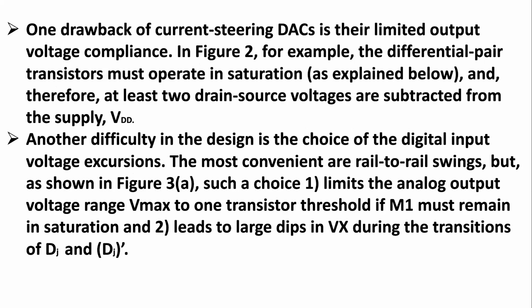In figure 2, for example, the differential pair transistors must operate in saturation, and therefore at least two drain-source voltages are subtracted from the supply VDD. Another difficulty in the design is the choice of the digital input voltage swings.